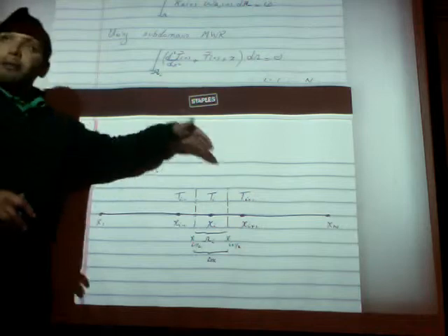By the way, at node xi minus 1, we have the discrete temperature Ti minus 1. At node xi, we have discrete temperature Ti, and so on and so forth. Same thing we did last class. However, in last class, all we did was just locally approximate, use 3 nodes to throw in a parabola, right? That locally approximated the temperature distribution using that parabola through the 3 nodes, and we use the same direct delta functions as weight functions, so that led to collocation, and local collocation led to finite differencing.